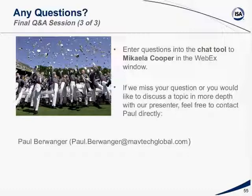Okay, next. We add low and high alarm limits to pre-warn the operator, and high-high and low-low alarms to cause a trip from the shutdown system. The operator has no time for action for this. So do you think it'd be a good practice to add another in-between alarm to give the operator more time to take some action?